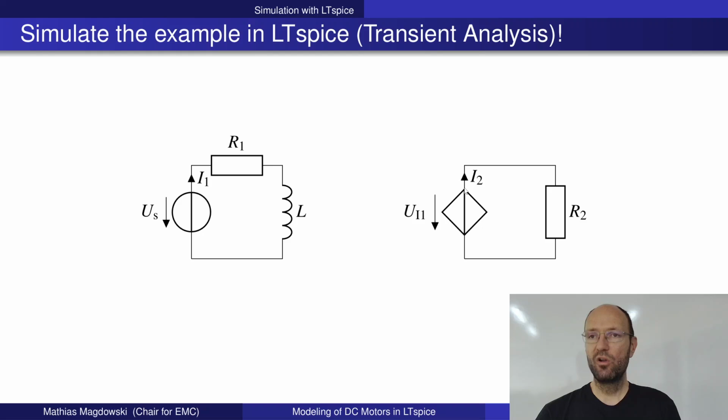So we have to go to Edit. And then there should be an option that is called Component. And if you click on this, there will be a huge list and library of all possible components that are there in this circuit simulator. And you can see that there are also analog to digital converters, there are comparators, filter components, operational amplifiers, switches, all kind of stuff.